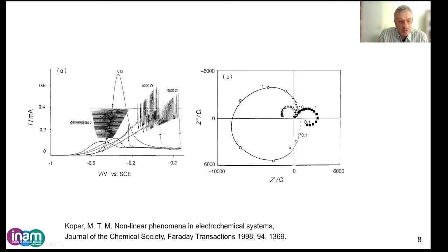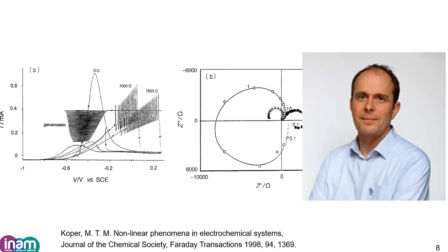authoritative analysis was done by Mark Cooper in the late 90s, and here is a bifurcation in JV curves, so that at some point the system starts oscillations, and this is associated to the impedance spectra. And again, one thing is related to another, so that the impedance can detect the bifurcation that sends the system into oscillation. This is Mark Cooper that clarified all this complex story.